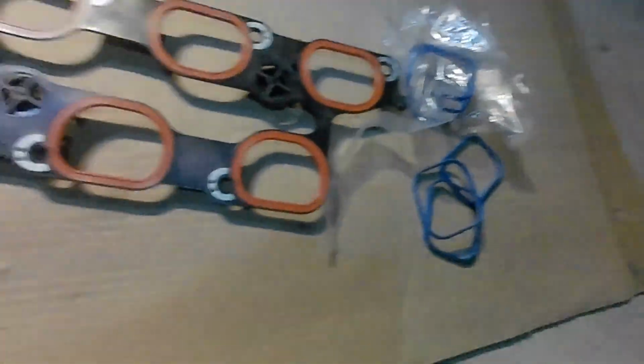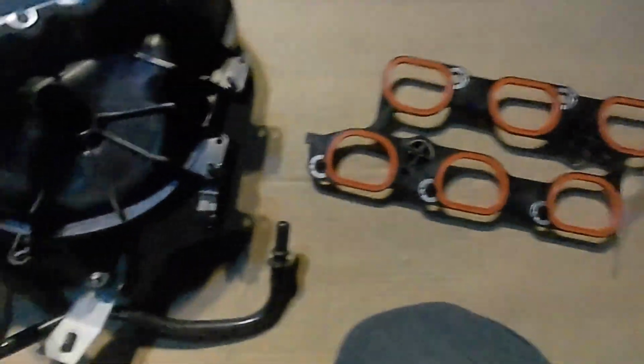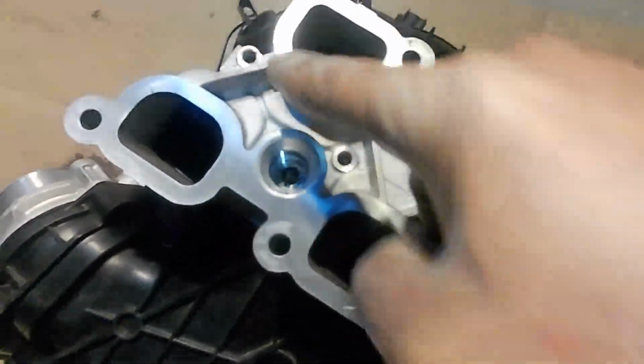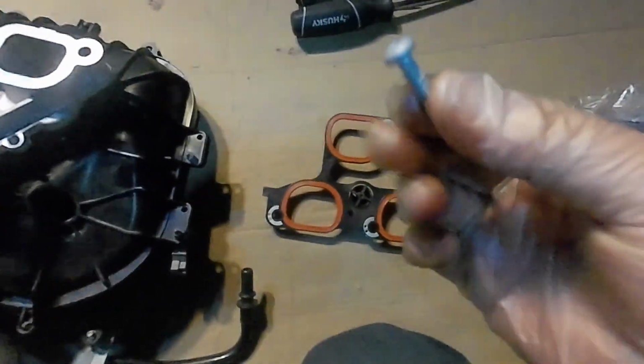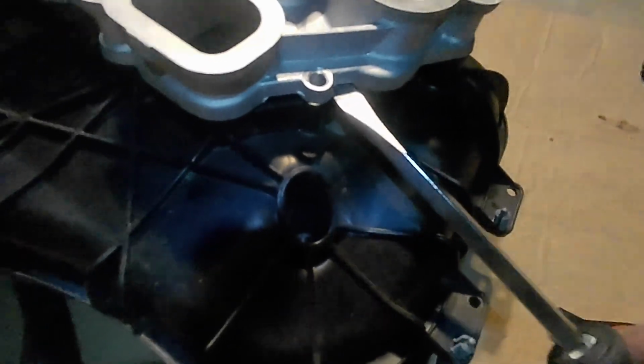The way you get to this is by removing 4 bolts here. They're hand tight, and you can just remove them with a screwdriver. Once you do that, you get a screwdriver, and as you can see here, there are little spaces around this intake part that you can use to put a screwdriver in there and try to get underneath from all corners, gently, from the front and the back.